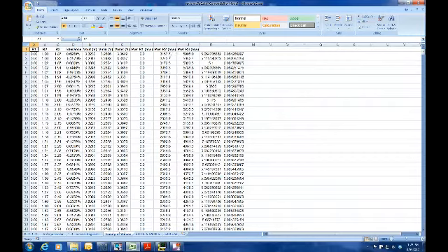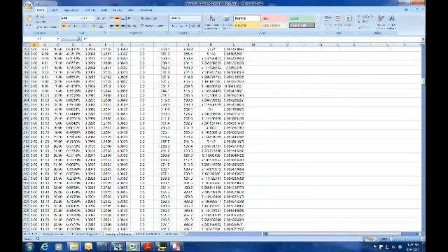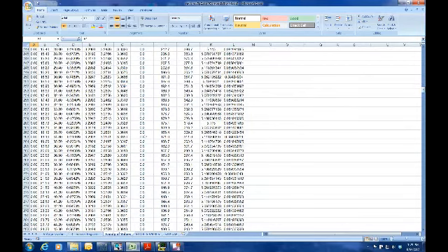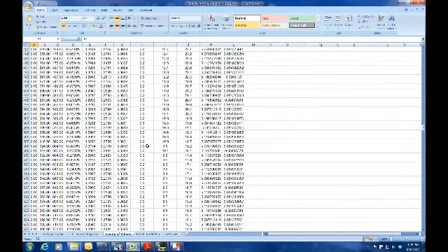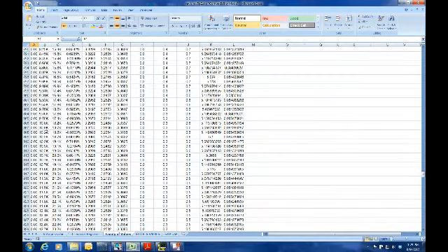So we start scrolling down, and we see we have a lot of values that will work, and we have various tolerancing on the output voltage. We'll go over that in just a second. So we get down here, and we get down to the k ohms, and let's see, we like to be around 10k ohms for our voltage dividers. So we see we have a 10k and an 18.2k, 300 milliwatts and 600 milliwatts. So we're okay. But we have an awful lot of values, and you know, the tolerancing isn't too good.